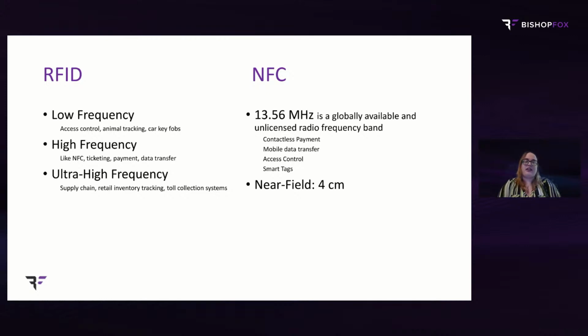For NFC, it stands for near field communication, and the near field is pretty literal, up to 4 centimeters distance. And as we talked about earlier, there were those radio bands that had certain licenses and purposes. So this is 13.56 megahertz, and it is globally available as an unlicensed radio frequency band. So in that spectrum, NFC can do a lot, and it is unlicensed.